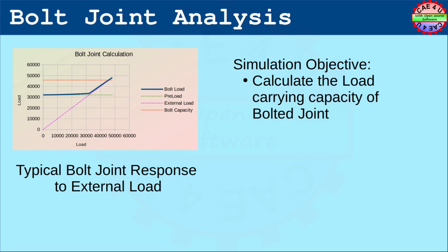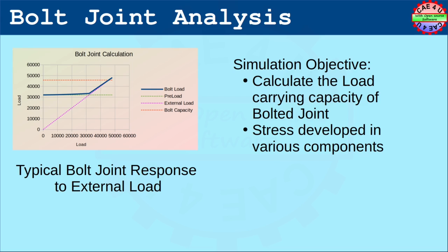Now let us set the simulation objective. We would like to calculate the load carrying capacity of the bolted joint, and we also want to see the stress developed in various components, and what is the contact pressure distribution between the interfaces. This is important to determine whether leakage can be imminent or not.